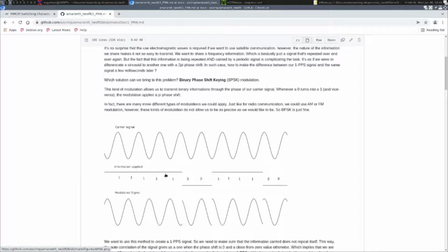Every time we have a 1, if we make a XOR operation, here for the carrier signal, having a 1 XOR 1 equals 0, that's how you get here the low state. And by having a 0 XOR high state, it equals the higher state, and so you get a 1, then a 0, then a 1, and this operation reverses the state of the signal.